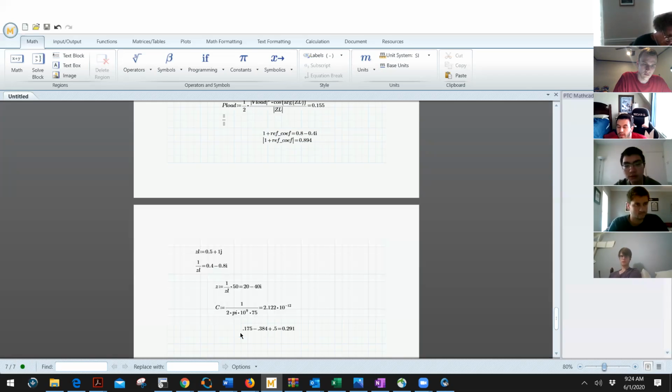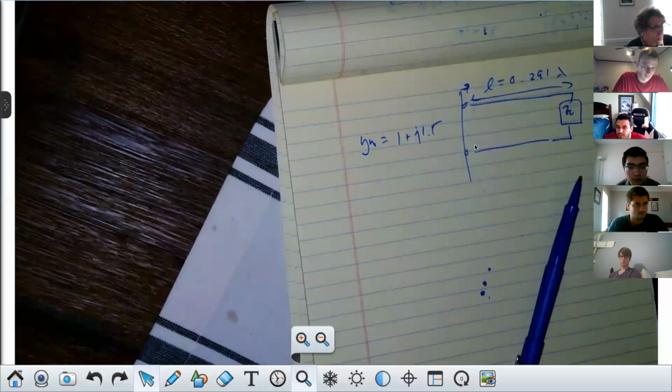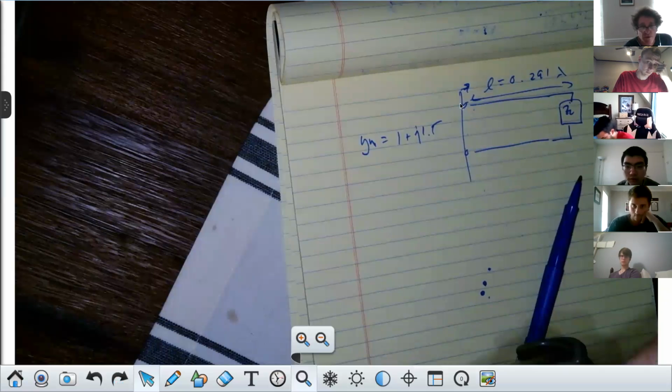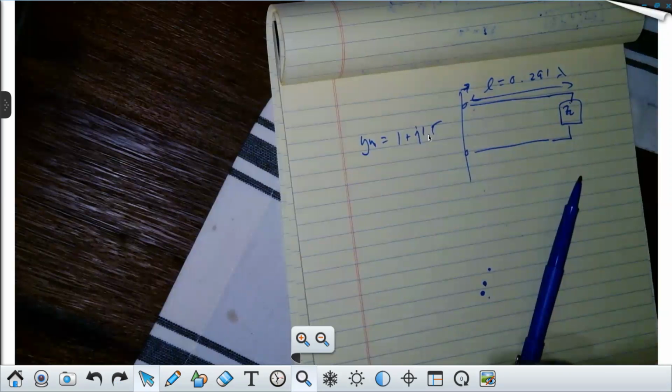Work with me on this one. Do y'all agree with that, class? Remember, this is in the admittance domain, so it's normalized admittance. You always go to the 1 circle. So when I hit the 1 circle, my first point is 1 plus j1.5. How many agree with that? It's just like before, right?